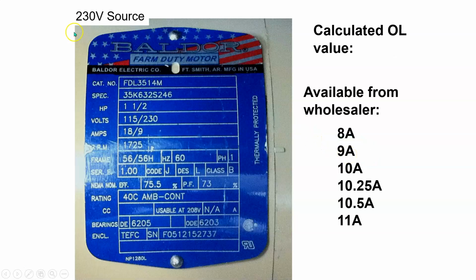And one more. So here again, a 230 volt source, 1.5 horsepower. It's 115 or 230 volts, so I'm going to choose the 230. The amps is 18 or 9, so it's going to be 9 based on 230 volts. Now I'm looking for my service factor. The service factor right here is 1, so it's going to be 1.15 multiplied by my 9 amps, which gives us 10.35